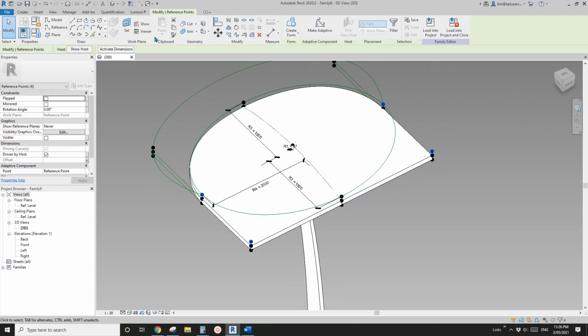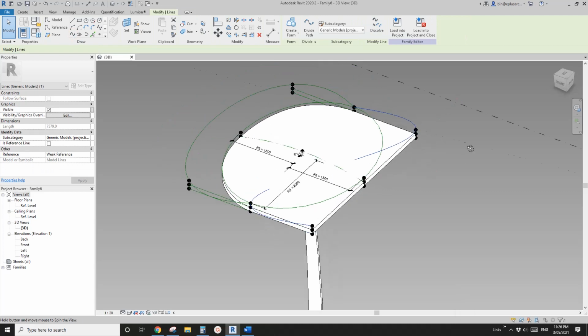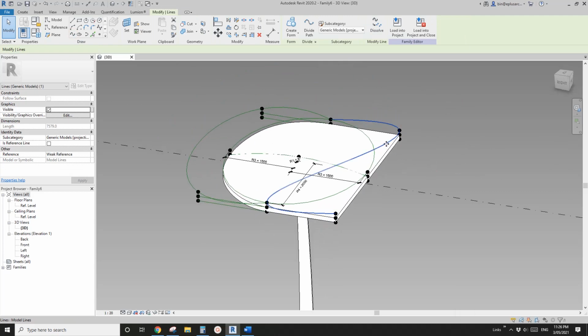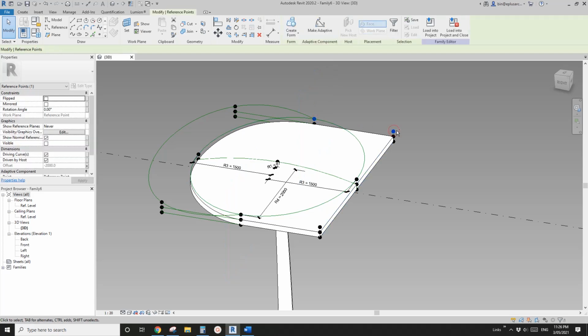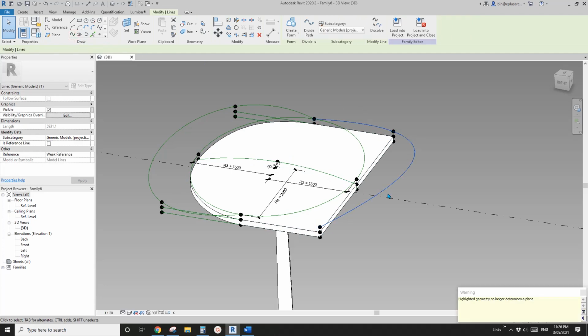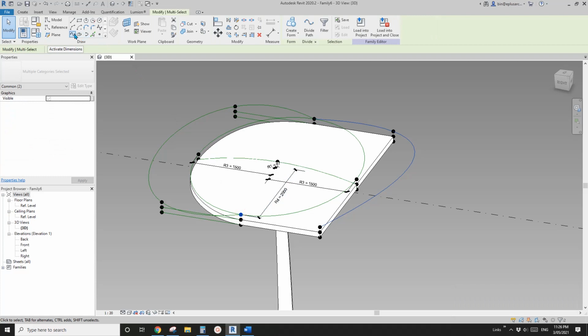Okay, I'll try. Select 4 points. If I create a spline, this is what we get: an S shape instead of a shape like this. So Control Z, let's do it again. This time 1, 2, 3, and spline. Then select this spline together with this point and the spline again.